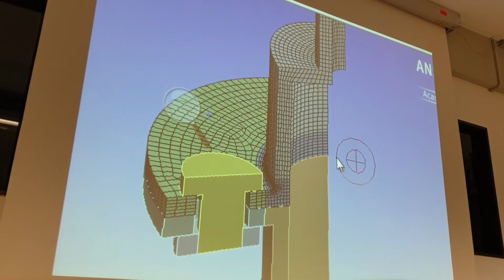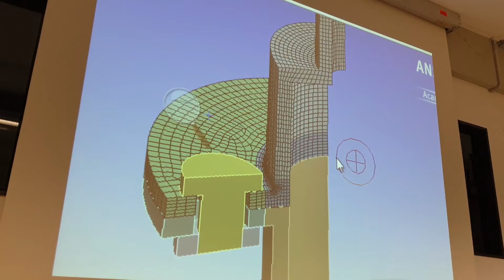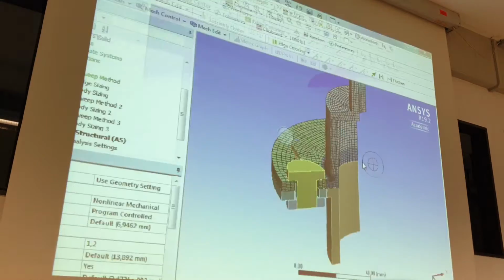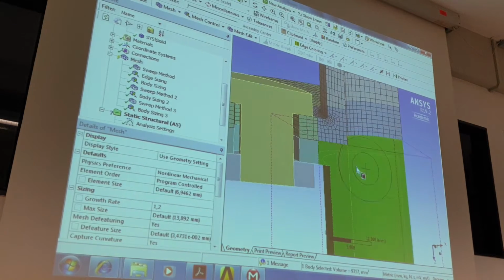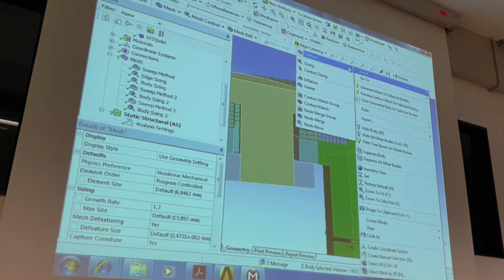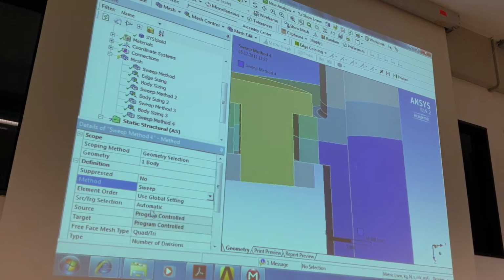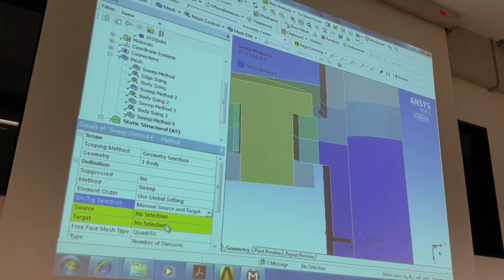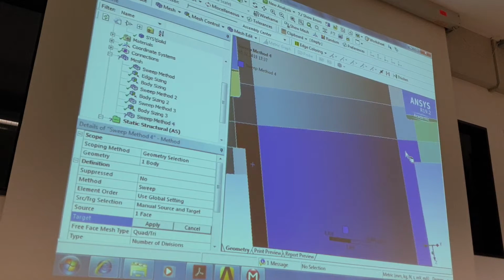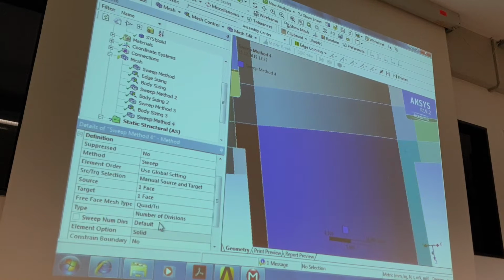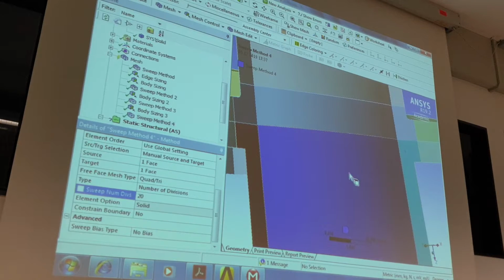Okay, of course, in 2 weeks we have to finish this task, and then we can create flow simulation. Same story, yes, I have other part. Right mouse button, insert method sweep, same procedure, inlet, outlet here, outlet other side, 20 elements, everything same, yes.